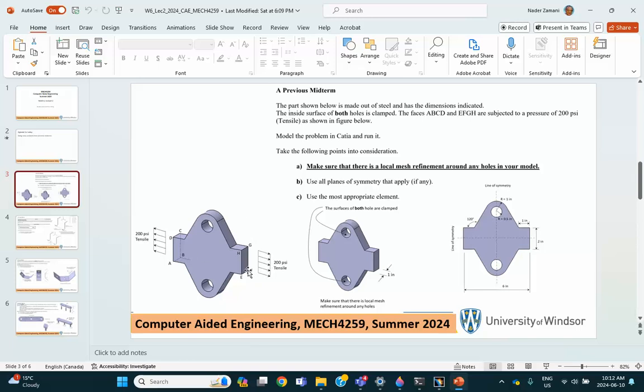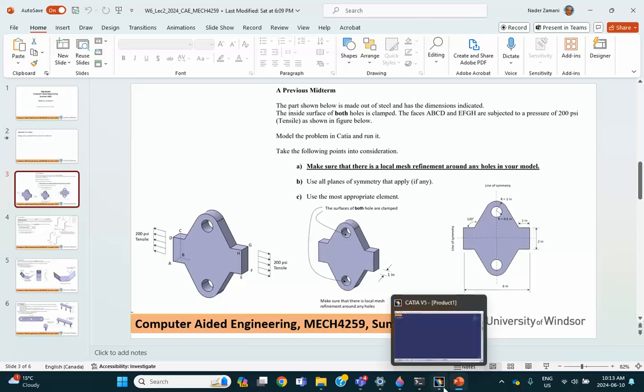In other words, you can cut it horizontally, you can cut it vertically, and you can cut it through the depth because of the way the load and restraints are acting. Now you have two choices: make the whole thing and then start splitting it with the appropriate planes, or you can make 1/8 of the model. Entirely up to you. I will make 1/8 of the model. Okay, so let's go ahead and do this.